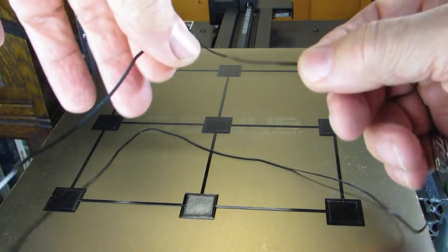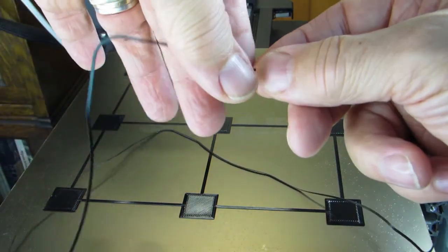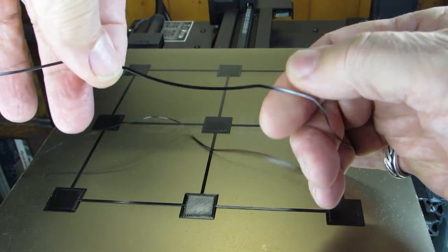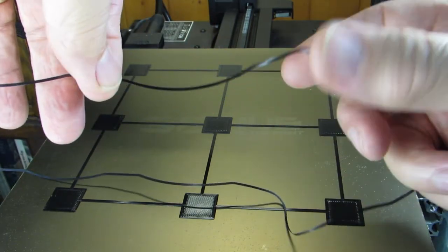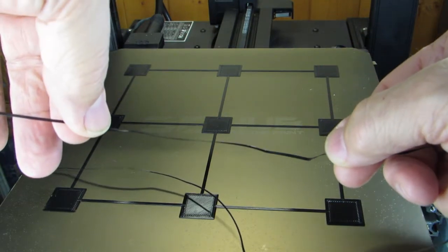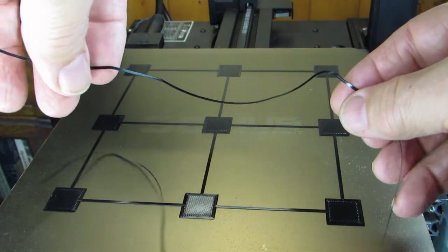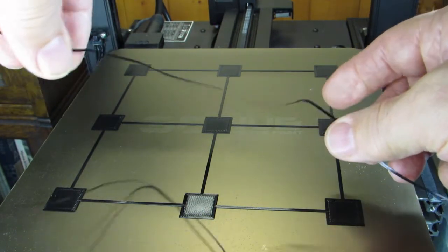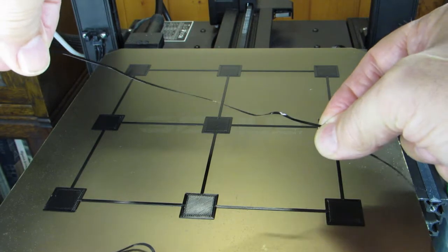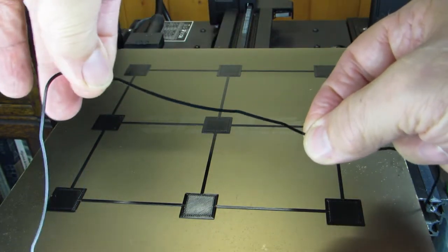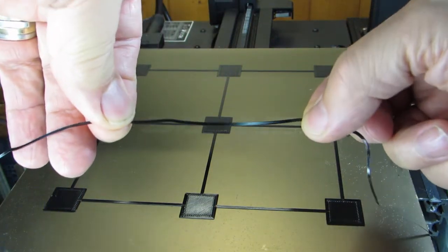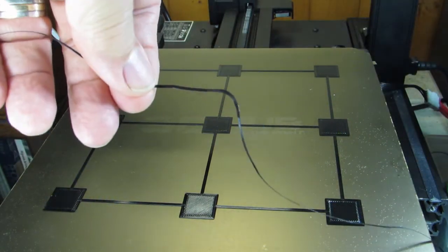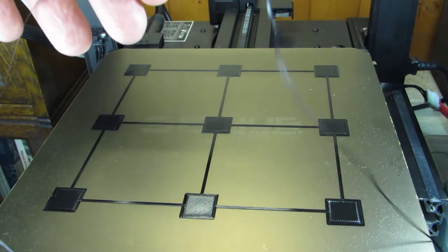I have had prints in the past where this came away as 3 separated threads, even though it looked alright on the bed. And I take that as a sign the lines didn't bond correctly, which can mean you're printing too far away from the bed. So the inverse ought to be true, right? This should be a good sign that we printed at a good distance from the bed because the lines all fused. We were not too high. It doesn't mean we weren't too low, but it means we were not too high.